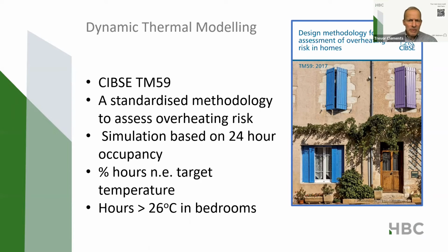It is a standardized methodology to assess overheating risk, and it does it by running a simulation based on 24-hour occupancy. And it sets a limit on the percentage of hours exceeding a target temperature, and also sets a limit on hours where the temperature will exceed, in theory, 26 degrees centigrade in bedrooms. So it's a pretty complex beast in itself.